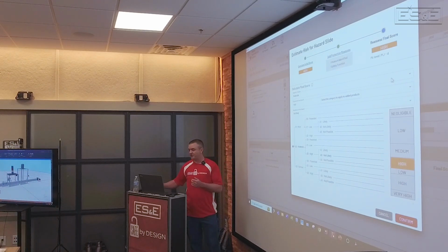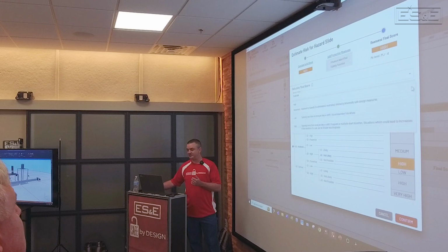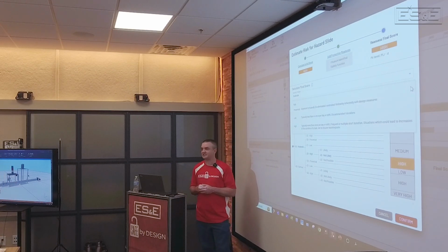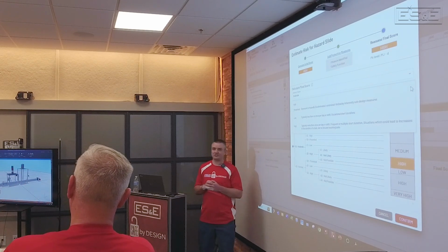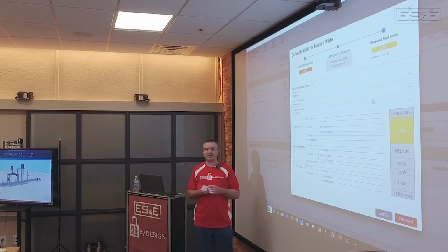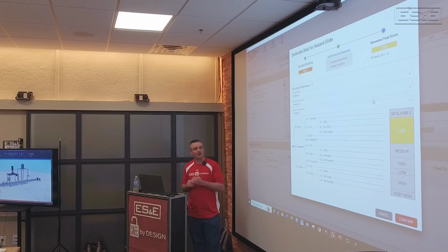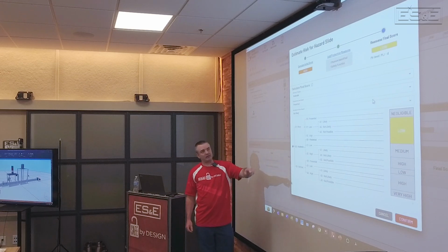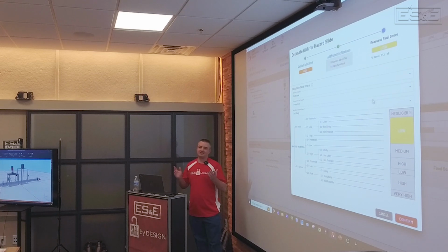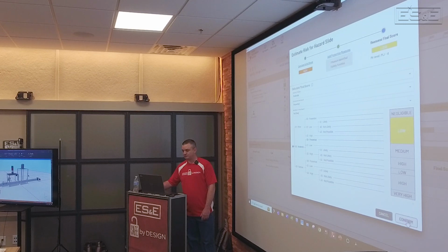Right. So when we look at our exposure to the hazard, this is where we have the choice of prevented. Basically, we've eliminated the machine from moving if he is standing in that position. So if he blocks that light curtain when he's loading that plate, there's no way that conveyor can move. I would say that would be prevented. And that's the job of our safety processor. It's going to do that logic, monitoring, and all that for us. You can see how this changed our matrix now to the low tolerable risk level. That's an acceptable level of risk, so I would call this good once we did this.